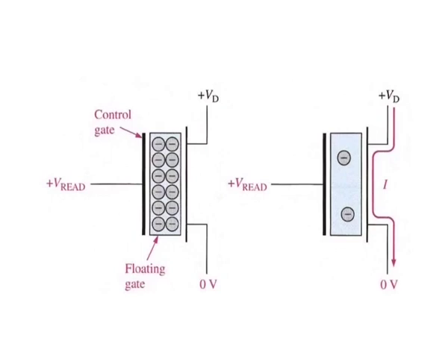So, the floating gate charge associated with a stored 0 prevents the control gate voltage from reaching the turn on threshold, whereas the small or 0 charge associated with the stored 1 allows the control gate voltage to exceed the turn on threshold. When the transistor turns on, there is current from the drain to the source of the cell transistor. The presence of this current is sensed to indicate a 1 and the absence of this current is sensed to indicate a 0.